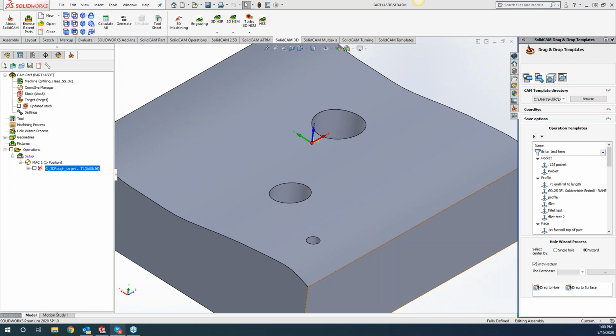Now, if I go ahead and save and calculate right at this point, here is what I see quite often: we have some gaps along our surfaces, as well as some of the end extensions coming up to a full retract, which is completely fine. This isn't going to hurt anything, but you can reduce all of those retracts and those movements going up and down.